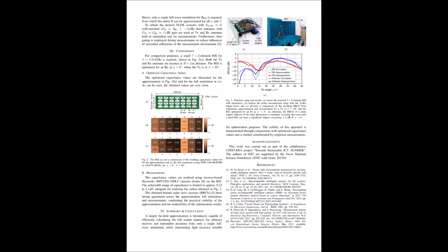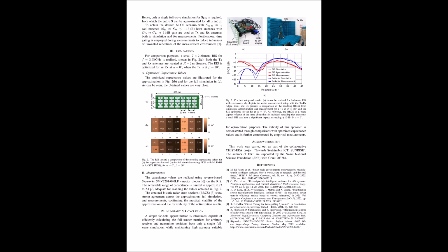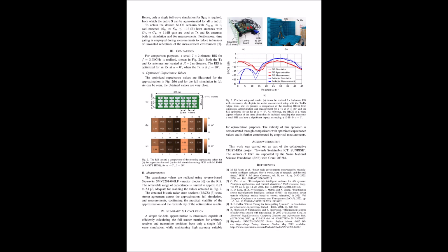I'm looking at it now, and there are antenna gains, distances, this exponential term. It's a bit much. Let's unpack it. So you've got the antenna gains. Those represent how effectively both the transmitter and the element on the RIS focus the signal. Then you've got the distance between them. That obviously plays a role in the strength of the signal. And finally, you've got that exponential term, which captures the phase shift that the signal experiences as it travels that distance. Ah, right, the phase shifts.